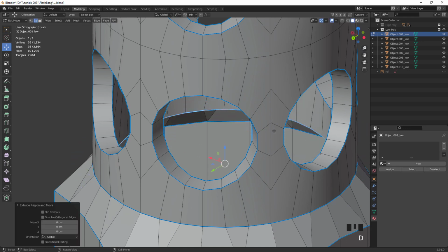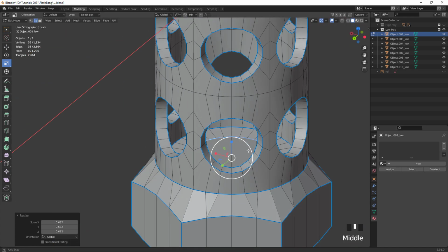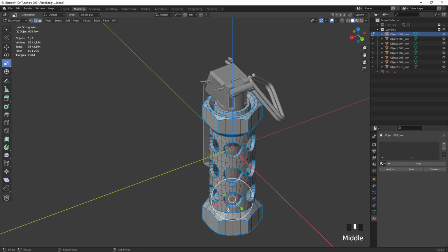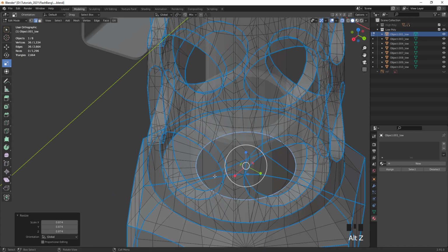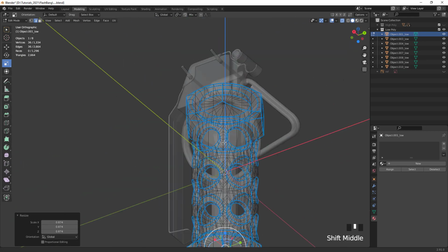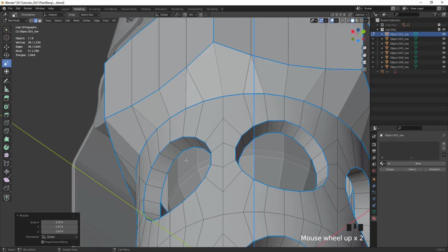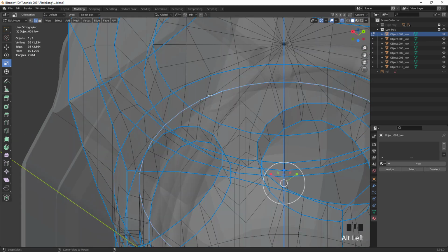I'm gonna make an edge loop and then just say D for extrude and let go of the right mouse button. And then we can just scale that selection in here like that, because we don't want to cap it all the way through. That will save us some space on our texture once we get to the unwrapping in just a moment.